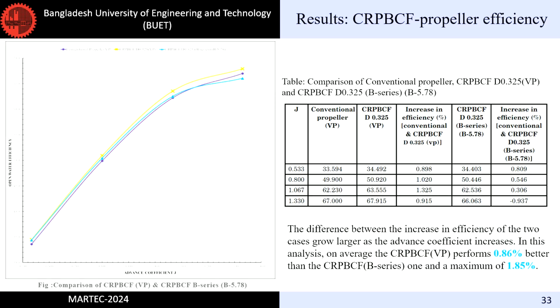After making the comparison of the diameters, we have chosen to compare two different types of contrarotating propeller-Boscap fin. Here with the similar design, we chose the main propeller for the auxiliary propeller, and a B-series propeller of the same pitch by diameter ratio and blade area ratio. All the dimensions are the same except for the blade sections themselves.